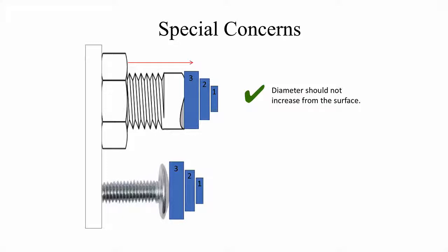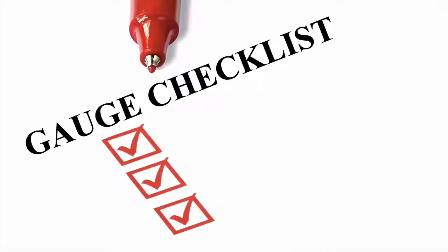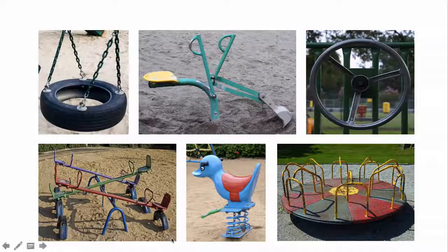In the second picture, you can see that the diameter of the protrusion is not the same size from the surface to the end. The protrusion passes the three-gauge test because the outer element is wider than the area at the base of the surface. Although it passes, this still causes a protrusion hazard because it causes a hook-like effect and can entangle children's clothing. Therefore, we advise that child care centers use materials that not only pass the three-gauge test, but also eliminate the possibility of entanglement.